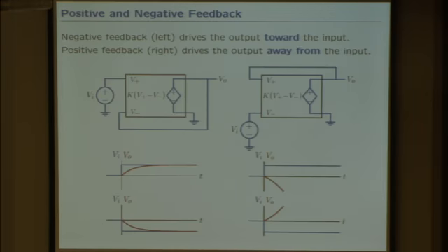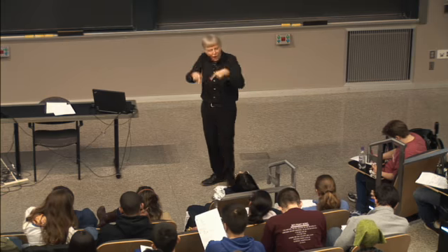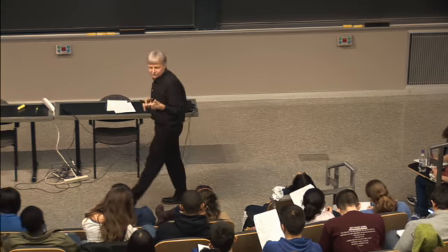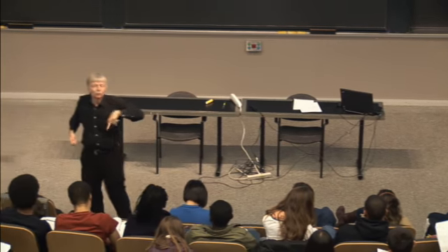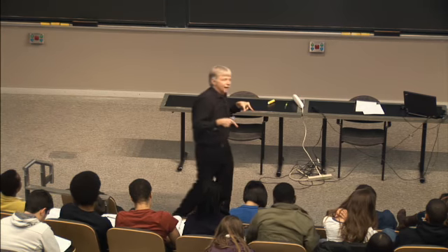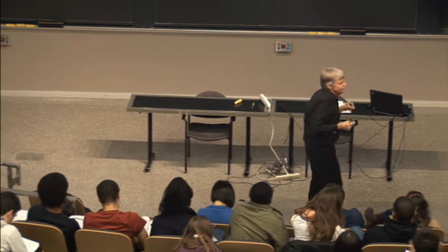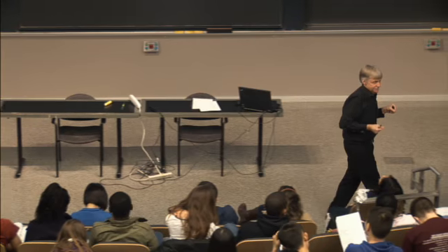So by thinking about the flow of current, what's the op amp actually doing? The op amp's actually sensing the difference between the voltage at the positive port and the minus port, and it's sourcing current that changes the output voltage to go up or down. You need to wire the op amp so that ultimately the output equals the input. Otherwise, the ideal op amp condition that V plus equals V minus will never be attained.